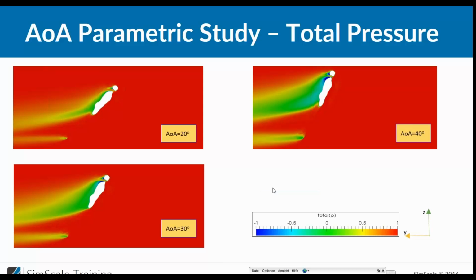Exactly, and the reason behind this, if you remember this concept that Mila talked about, the adverse pressure gradient, is exactly what's happening here. So when you increase your curvature so high, then you will have this pressure difference, and then the flow cannot stay attached to the surface, and that's why you have this low kinetic energy bubble or separation region. So it's all about the right position, or the right angle of the athlete according to the free stream.